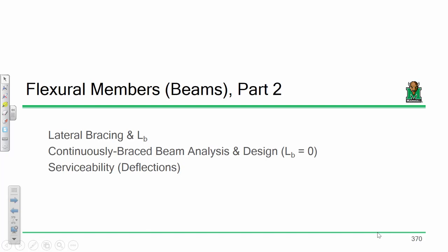So I'm going to just eyeball it, and we'll say that this one was like 0.2 L, and this one was 0.8 L. Does that seem like a fair assessment? I'd argue that in terms of bracing, the one we really needed to worry about was this one right here, that this is 0.8 L. The short explanation I want to get across is that the longer that unbraced length gets, the bigger this value gets, the weaker the beam, okay?